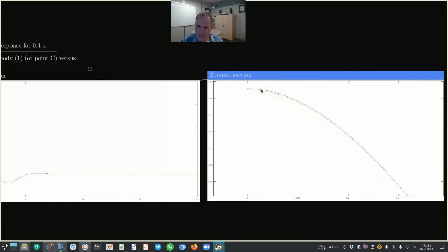And you can see a slight offset from the 3-body simulation represented by the blue line. The dotted line here, and I think it's colored yellow, it's not very visible here, is now where we've also replaced the bottom link, which weighs 2 kilograms, with a revolute joint. And now you can see the impact of that is more significant.